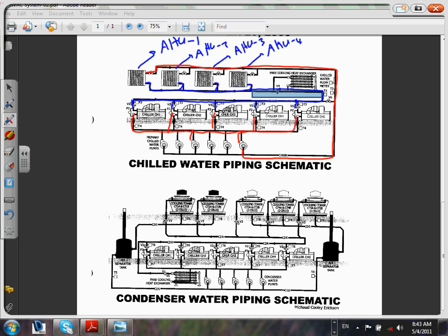And you really don't, as I said, need to know all this, but it really makes your life much easier. So after the water has been chilled, after you blow the air out of these coils, the water inside the coils becomes hot. So they take it back. Look at that. How do they take it back? Through pumps. They pull it back into the chiller, and they chill the water again and keep rotating the chilled water into the air handling units.